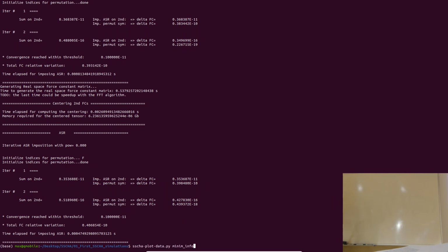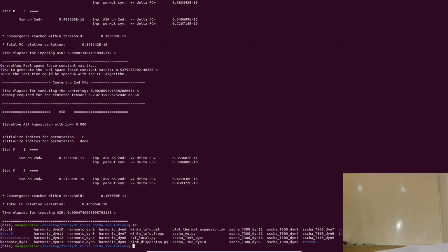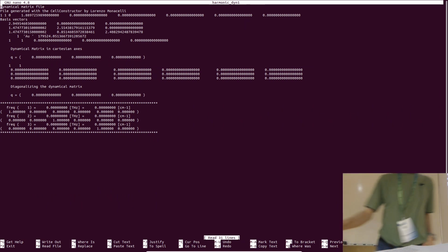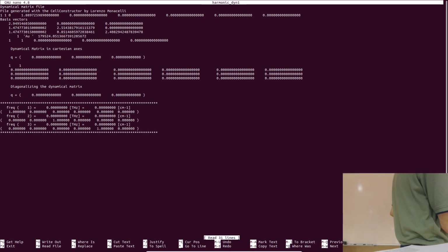But if you go to the output dynamical matrices, which are written in Quantum ESPRESSO format, these are the final auxiliary dynamical matrices. There, in the header, you have the structure written in the Quantum ESPRESSO form. So this is, let's say, the final centroid positions of the minimization. So there is the Quantum ESPRESSO dynamical matrix file that you get in the output, and then you have the final basis vectors and the positions of the atoms, which in this case is FCC or BCC. But this is where you have your final information on the centroids, right?